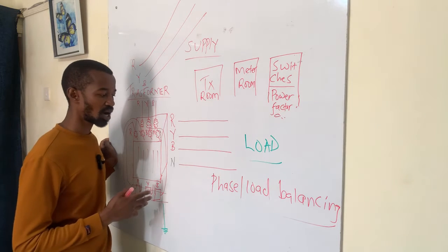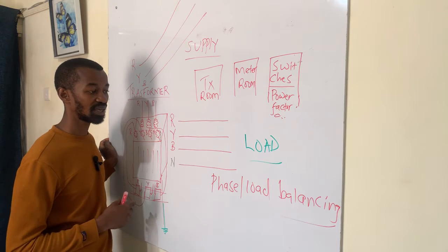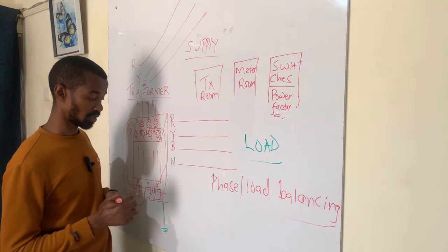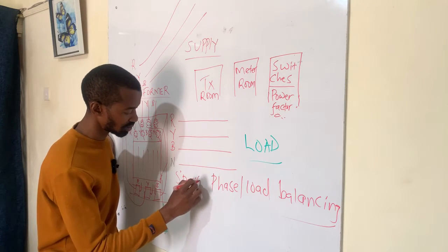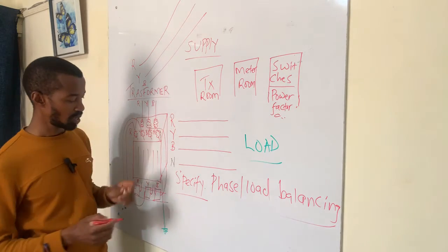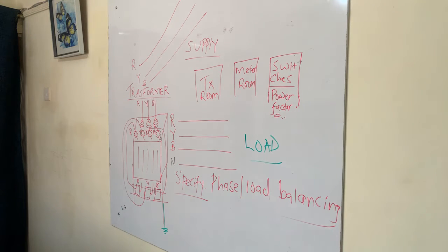Because if you say that you just have lighting points, you have sockets where you will be connecting the load for the customer there, and you do not specify, you need to do a specification so that the national utility will be able to understand clearly what type of load you are being connected to, as well as what is the expected total load that will be there.